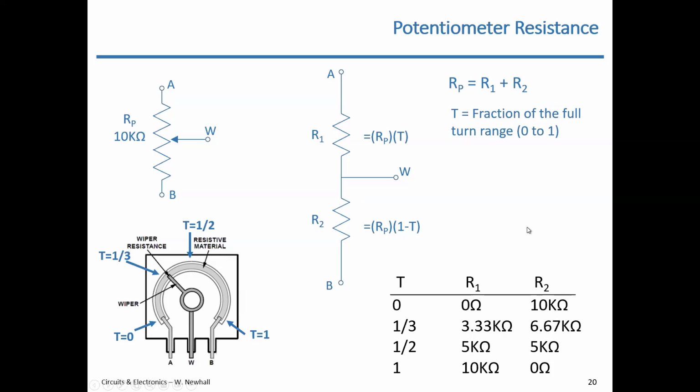So I'll leave that till later, but a potentiometer could be used as the input from a human to give a signal to something that's controlling pulse width modulation or other approaches. But you wouldn't use this as like a resistor in series with a light bulb because it would be very power inefficient.